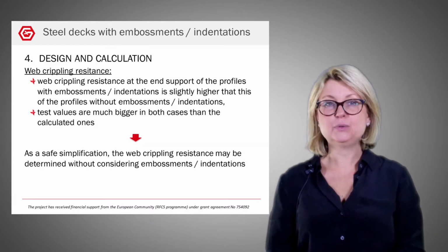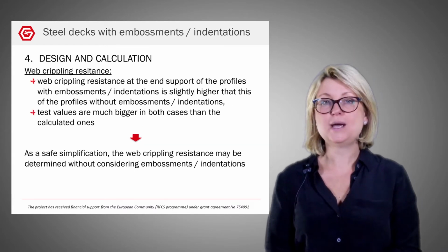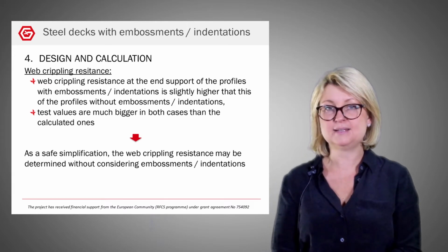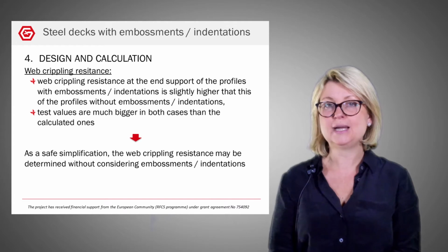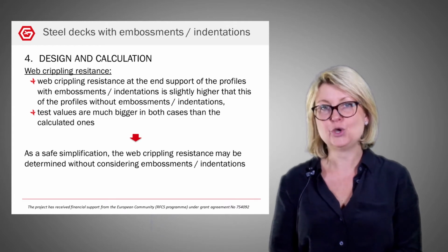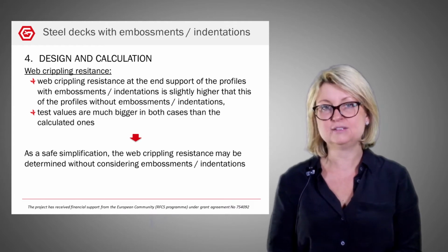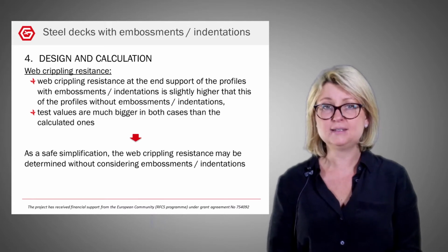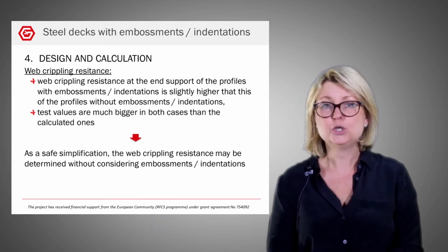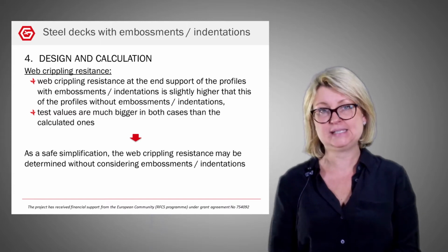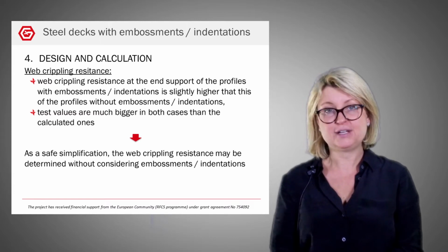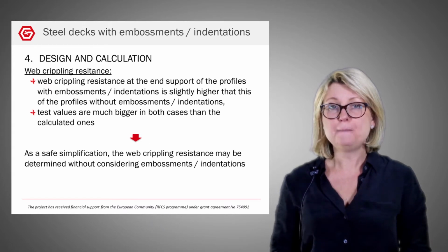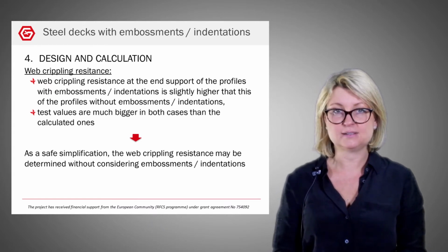For web crippling resistance, it was quite different, because for profiles without embossments and indentations, the calculated web crippling resistance was much lower than the tested one. It confirms the observation highlighted in the literature, showing that the web crippling resistance is significantly underestimated compared to the testing results.